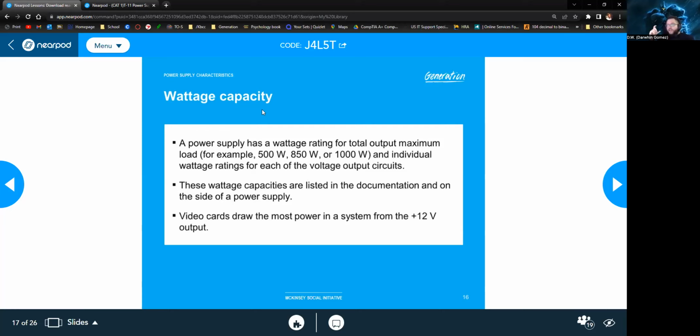So we have a specific rule, basically, because each component has an amount of wattage that it needs, right? So what you do is you take all the components that you plan on using and you add them up, right? This is going to give you the total watts that you need, the bare minimum power that you need, right? And then you go above that.